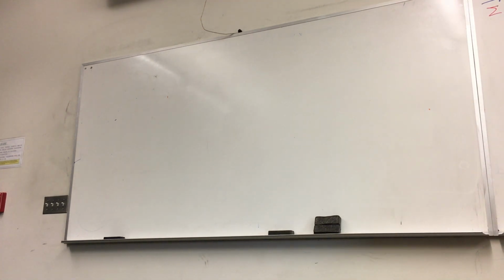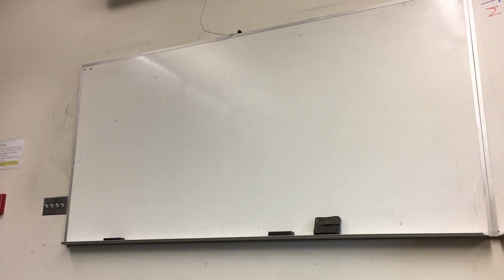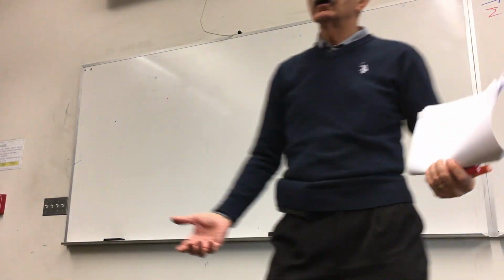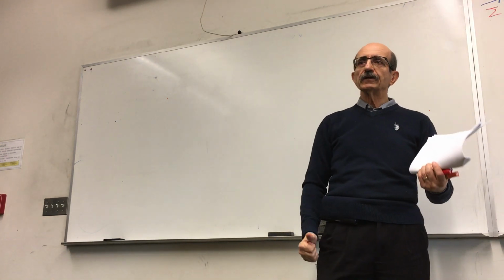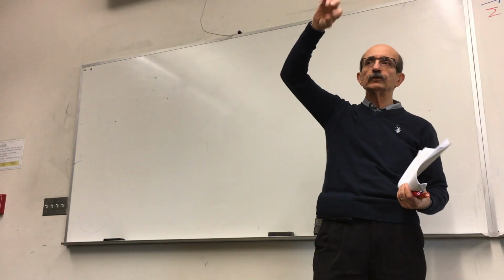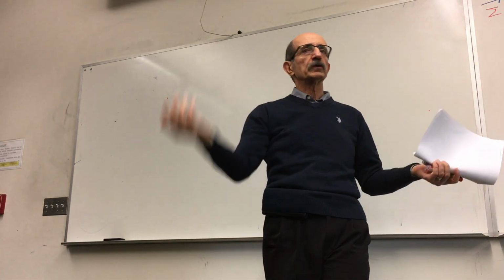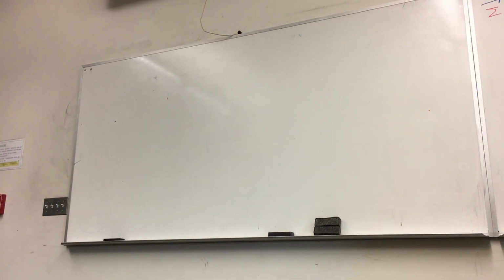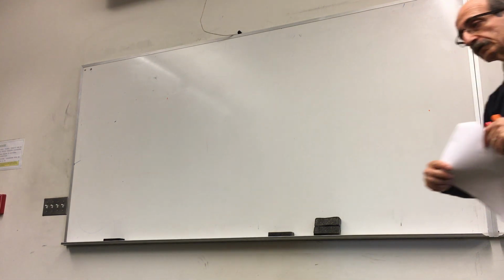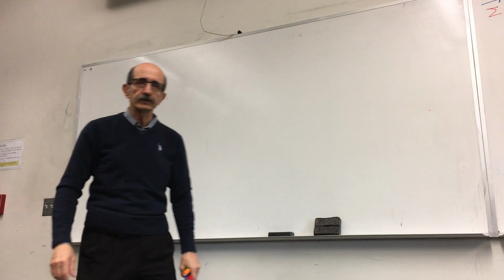Yes? So when it's in 2D and you find the moment, it's just like the number with the direction. It's not in components, but when it's in 3D, you need... You mean as far as the moment, you're talking about moment? Yes, because in 2D, all moments are acting perpendicular to the plane of x, y. But they're either along the positive direction of z or negative direction of z, which means either they're clockwise or counterclockwise. That's why 2D is so much easier, because all you need to worry about is just adding up the magnitude considering the algebraic sign, which is clockwise negative, counterclockwise positive.